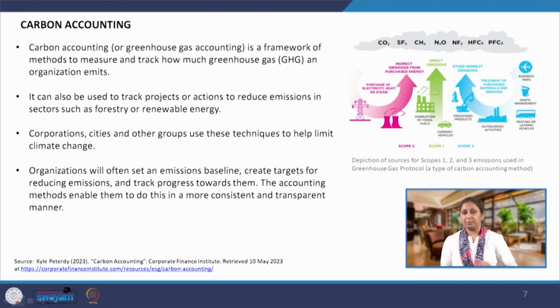For example, I was talking about reducing the requirement for HVAC, and how do we do it? We make the buildings comfortable. All of you, wherever in the world you are, you must have seen the traditional buildings being built in that manner, that they require least amount of energy and still maintain comfortable indoors. You go in extremely cold climates, they have very thick walls. You go to extremely hot climates, the deserts, they have very thick mud walls. Now, compare that with a multi-storied building which is using glass as a material. So, thick mud wall and a thin glazed facade.